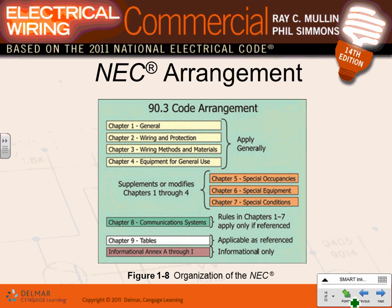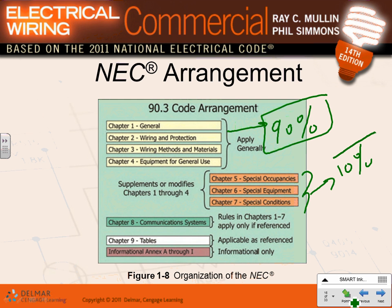Then it's published. Okay, the single most important thing, guys, about the NEC code book, please understand this fully. The code arrangement, chapter 1 through chapter 4, this is where you're going to spend probably 90% of your time. 90% of a lot of people's time is going to be spent in chapters 1 through 4. You have the general, wiring protection, wiring methods. Every single wiring method is covered there. And equipment for general use, transformers, generators, and a bunch more. Close to 90% of your time.